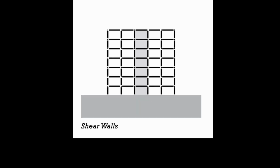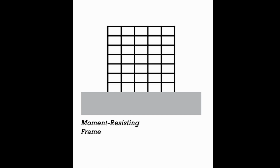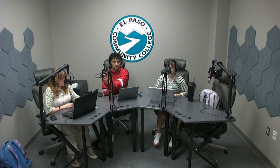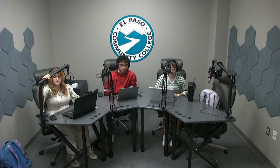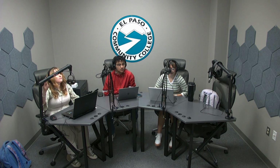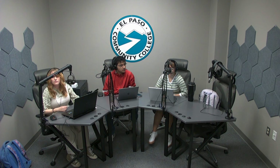Shear walls are stiff, solid walls made of reinforced concrete, steel, or less frequently reinforced concrete masonry. The moment resisting frames rely on stiffer moment connections between beams and columns to impart lateral stiffness to the building frame as a whole. In any building, the lateral force resisting elements must be arranged in a manner that is structurally efficient as well as conducive to good architectural planning.